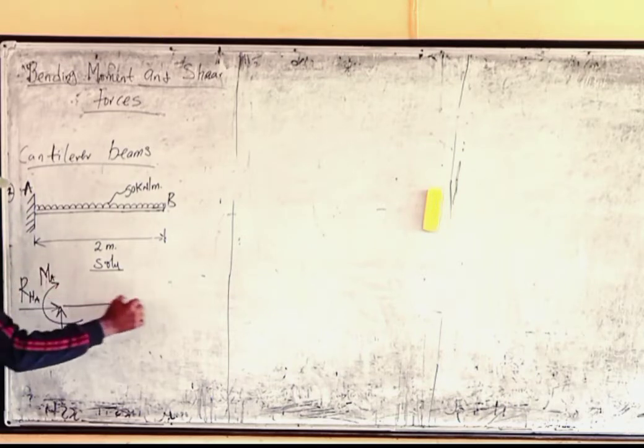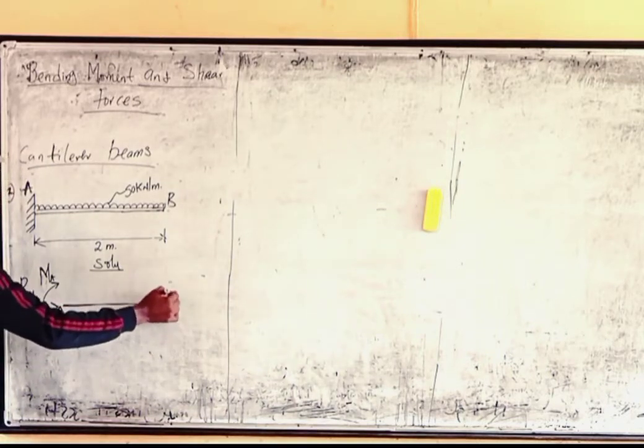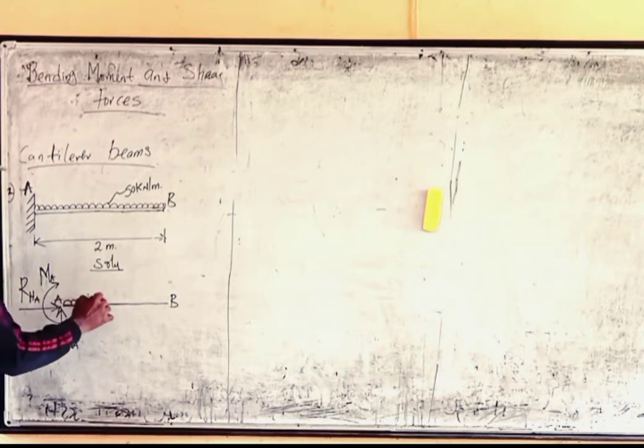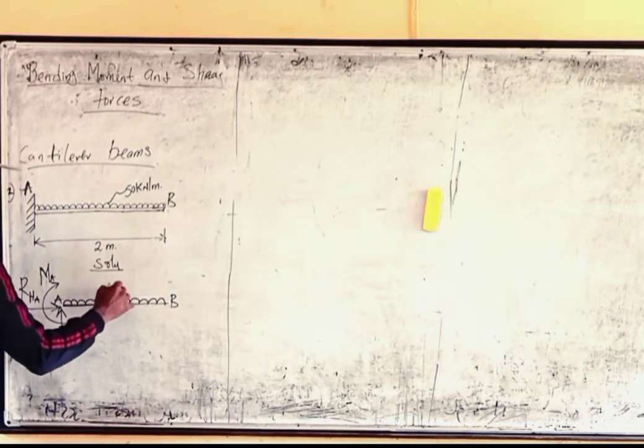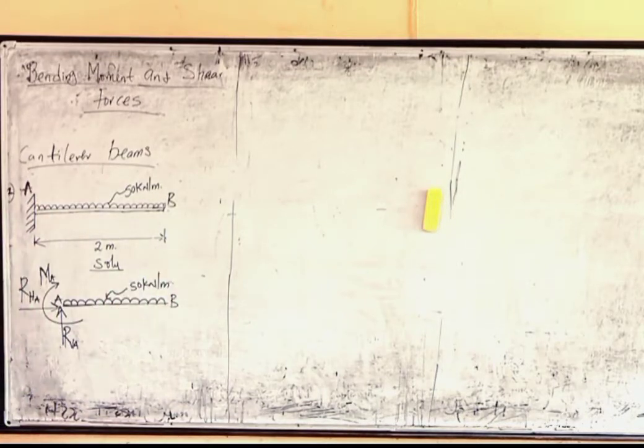And this is the beam. Let's see that as the beam. So this is point B, this is point A. It has a load of 50 kilonewtons per meter. So the first thing we're going to do is to calculate RA, something like RV, because RH for the horizontal direction is 0 because there's no horizontal loading. Then we can calculate RV by using the sum of the upward forces equal to the sum of the downward forces. So our RVA will be equal to the downward force,